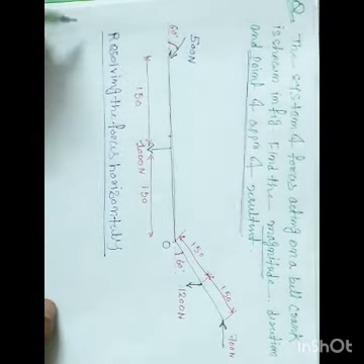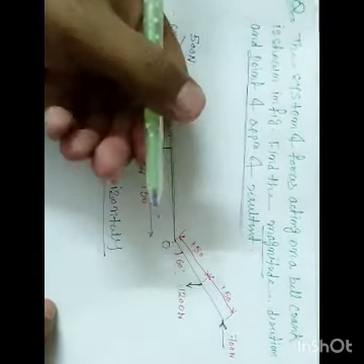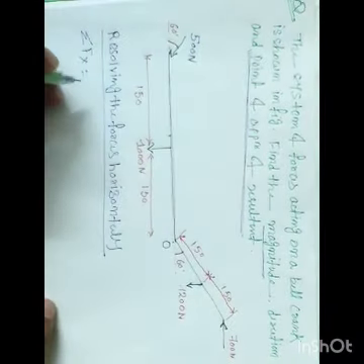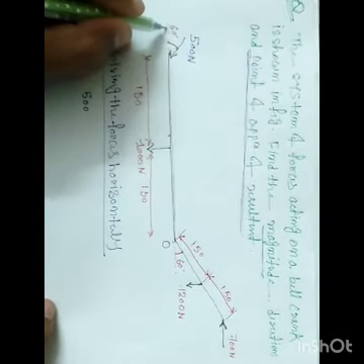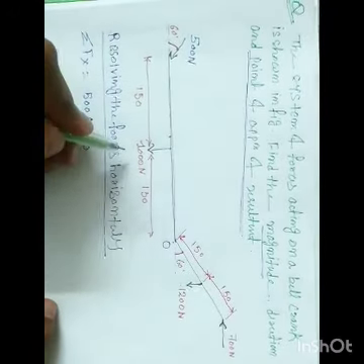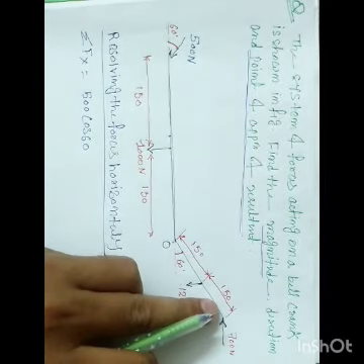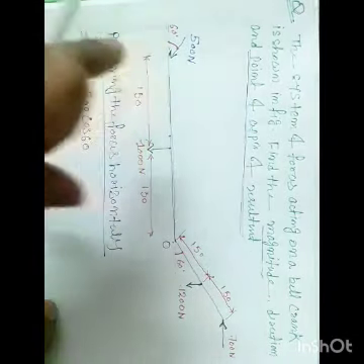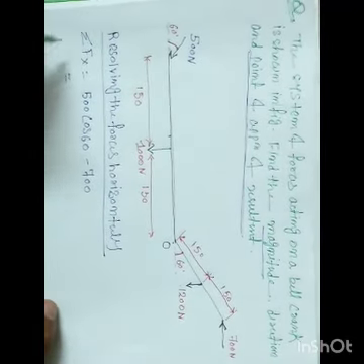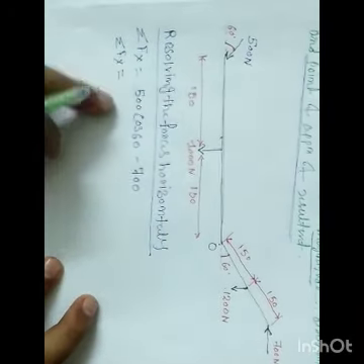So quickly you can find that summation of Fx is equal to what? It is going right. Why? Because the arrow is like this, so horizontally it goes towards the right. So it is 500, and the inclination is with the horizontal, so the horizontal component is cos 60 degree. This is vertical, we need not take. It is also vertical, we won't take. And this is the 700, exactly horizontal towards left, so it will be minus 700. Okay, now you can get the summation of Fx value, right? Then I'll put this value later on.